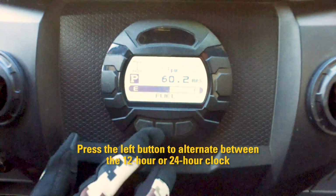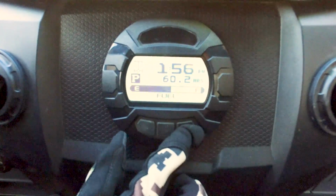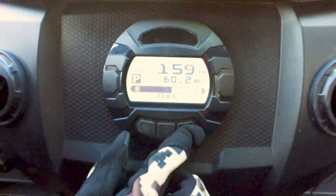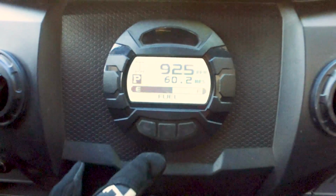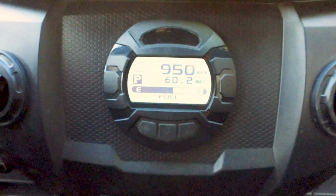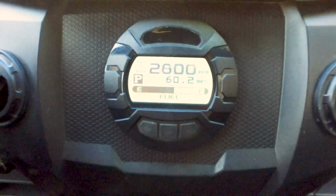Press the left or right button to set the hour, then press the middle button to choose the minutes. Press the left or right button to set the minute. When the proper time has been set, press the middle button to return to the main gauge display. When the tachometer function is selected, RPM will be displayed.